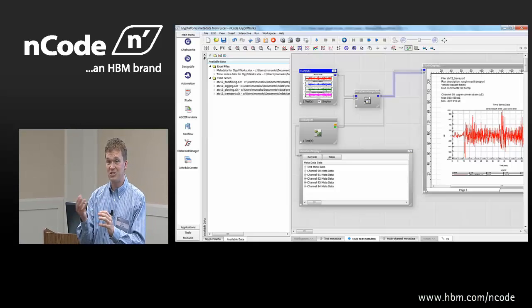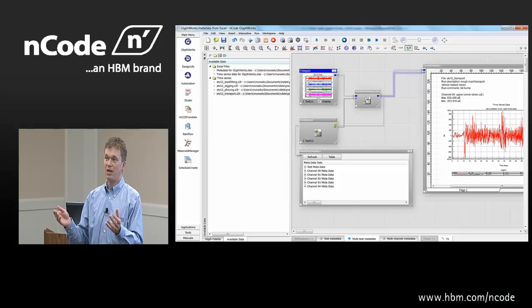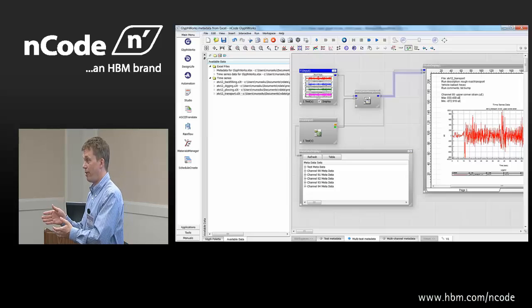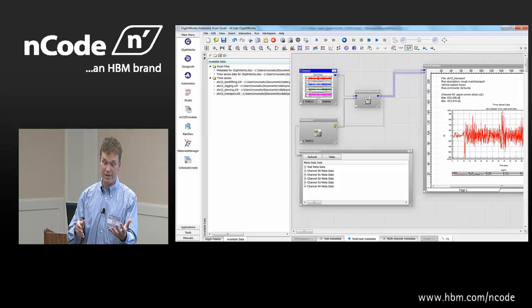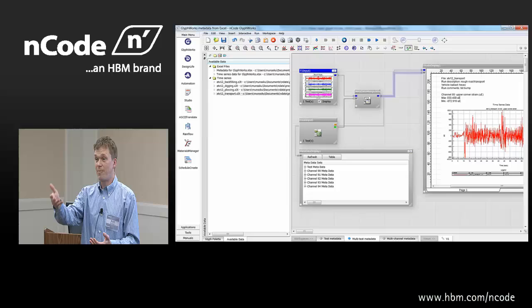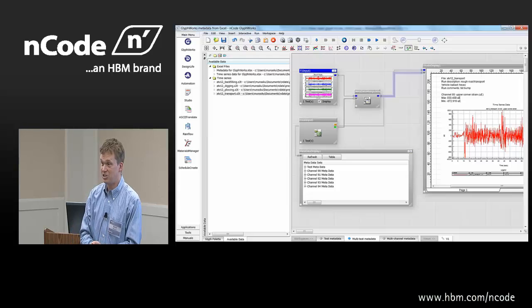So all strain gauges that pass through that glyph will be assumed to have an SN curve or an EN curve for cast aluminum. But then you say, hey, wait a minute. I only have 3 gauges on a cast aluminum part. I actually have several near a weld, a couple others on a carburized tube of steel, and so forth. So how do we deal with channel-based calculations?